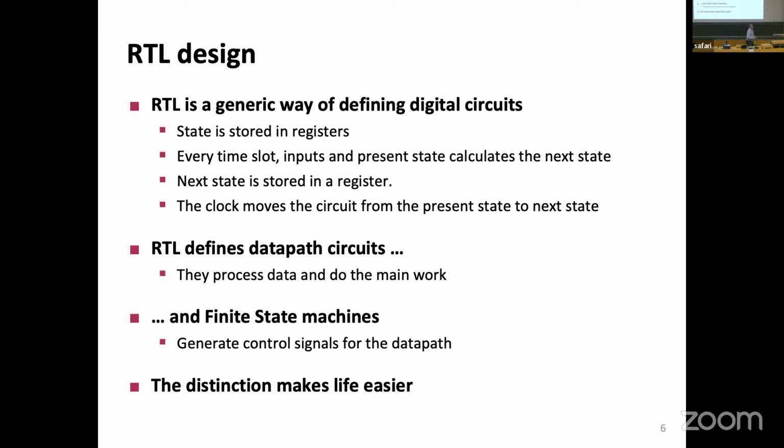Now, we talk about RTL design, and RTL stands for Register Transfer Level. And registers are the state holding elements when it's not 1 bit, but 32, 64, 256 together. And it means that we are describing what happens when we move from one register to the other register. We say the description is defining what happens between consecutive state holding elements. That's why we call the design flow usually RTL design.